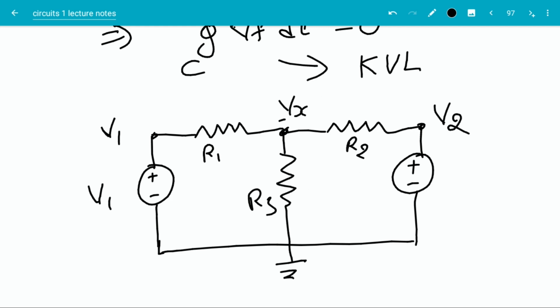We're going to take the same example circuit again, and note that I have already defined the potential function on the circuit. And as we discussed, as soon as I define the potential function on the circuit, and while solving the circuit, I'm going to make sure that the potential drops across all the branches are consistent with the potential function I defined. As long as I do that, all KVL equations will be satisfied. So I don't have to worry about KVL equations anymore. I only have to worry about KCL equations.